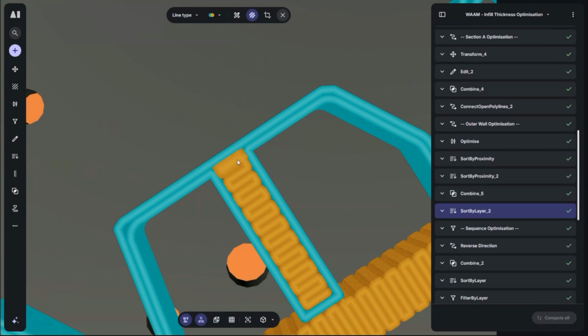And in wire arc additive, it's not usually the case where you change parameters dynamically based on speed and thickness, like you can with a polymer extruder very easily. Just change the RPM, sequence it, or synchronize it with the speed of the robot. Usually you're a lot more fixed to a set number of parameters in WAM.